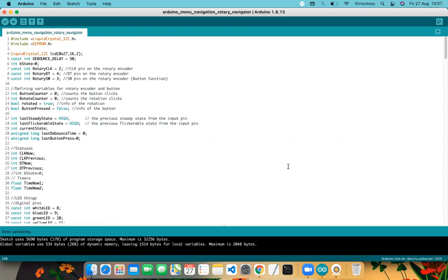You can try it out, and you can come up with your OLED solutions of RGB, what we had discussed just before that. If you have an OLED display, you can come up with the OLED, or if you have an LCD, you can come up with the LCD. But I prefer to go with the OLED, because the OLED is much wider than this LCD. The LCD can have only two rows, but with OLED you can have multiple rows. You can keep on playing with all such options, and then just by pressing the button, you can have the corresponding value selected for the options. So this is the advantage of OLED.